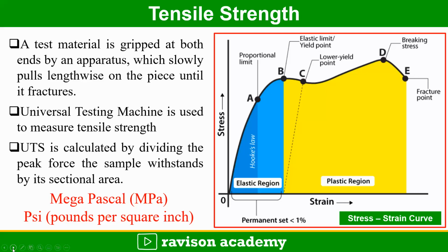So we will be conducting a test on the universal testing machine. We will be stretching the specimen to obtain the graph. So from the graph, we are able to find out the ultimate tensile strength.